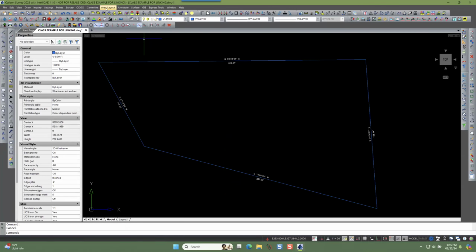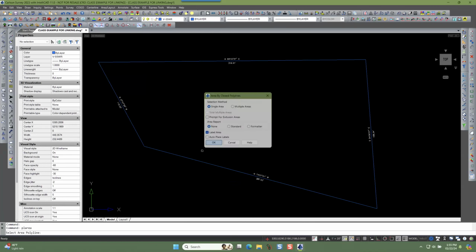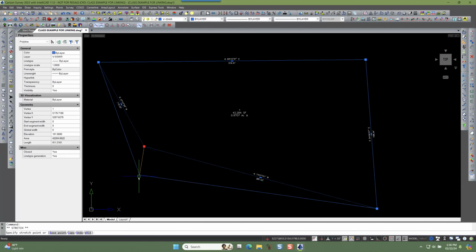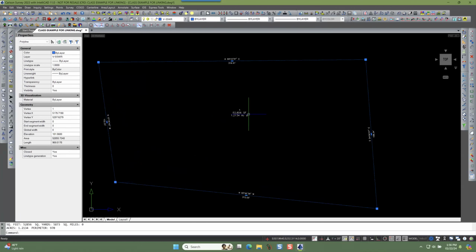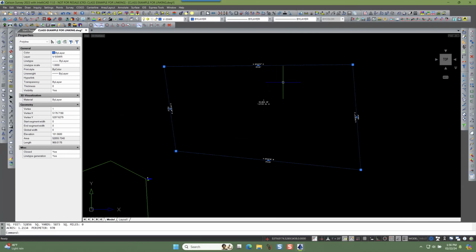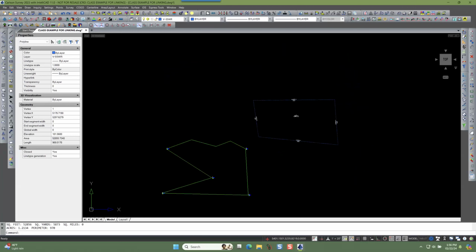Same thing as if I had my area by closed polyline. Right there. And then if I go back and do the same thing, notice my area values changed with that label as well. So that's also a label that was generated based on the geometry of that line work. So that's what linking labels with line work does.